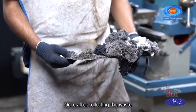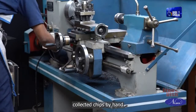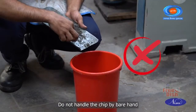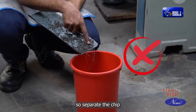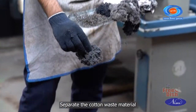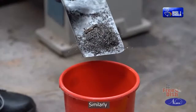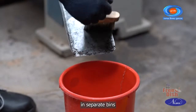Once after collecting the waste, separate the cotton waste. Collect the chips by hand shovel with help of a brush. Do not handle the chip by bare hand. There may be different metal chips, so separate the chip according to the metal. Separate the cotton waste material and store in the bin provided to store the waste cotton material. Similarly, store each category of metal chip in separate bins.